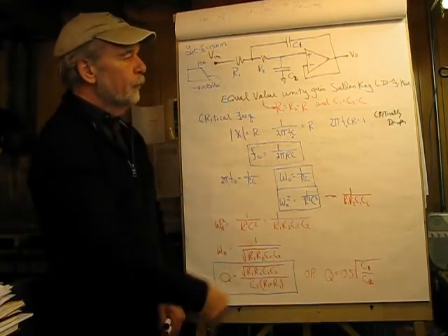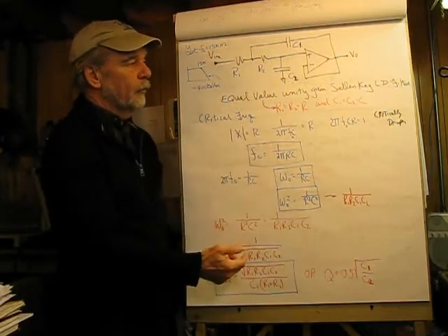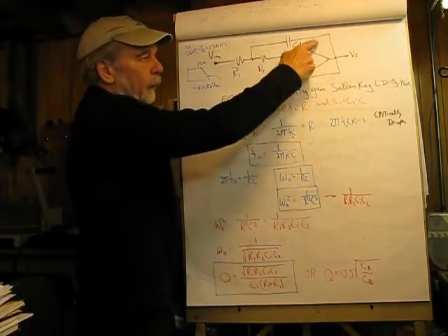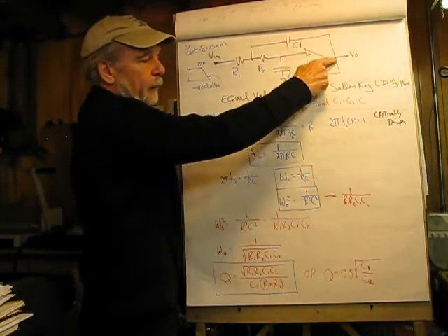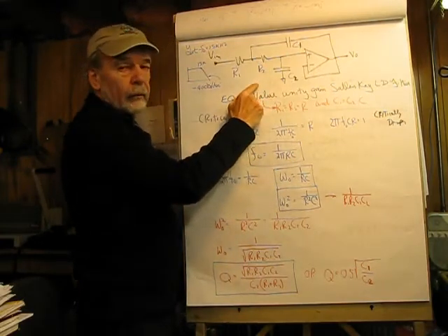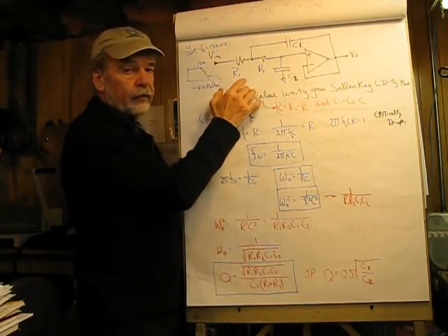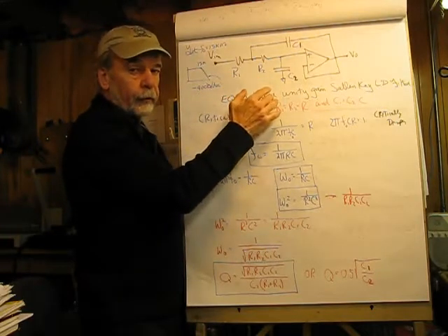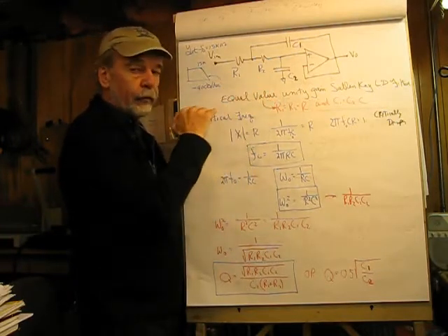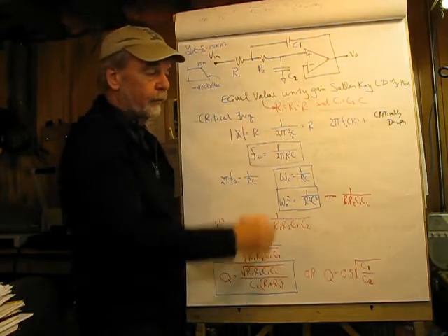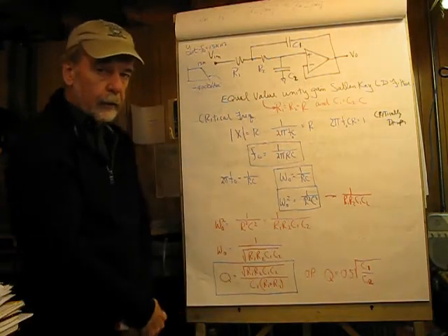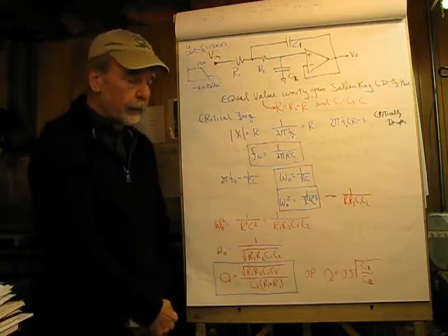And the circuit configuration looks like this, and let's pretend for a minute that I took C1, instead of connecting him to C out, I took him to ground. Now, that would just simply be 2 cascaded RC filters, and it would have a very, very lazy rounded roll-off and ultimately reach negative 40 dB per decade.